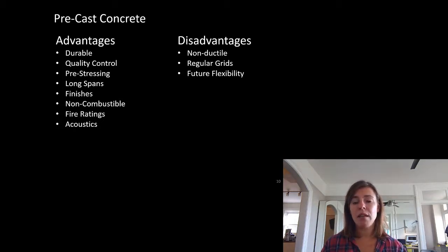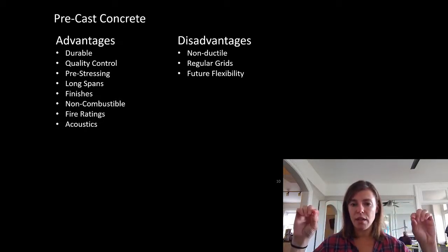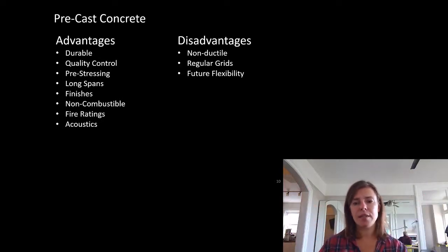But from 2010 to 2020, I can think of 5 or 6 projects at Blackwell alone where we see pre-stressing coming up in the systems. Core slab or hollow core systems, which we're going to talk about again going forward, actually made really smart use of pre-stressing in the development of their systems. They actually have strands of steel instead of rebar tensioned inside those slabs.